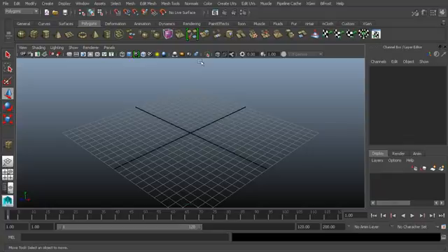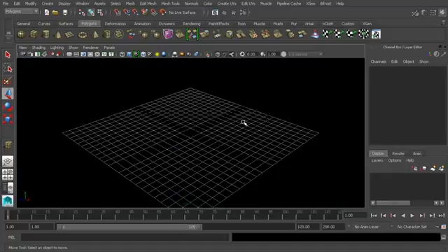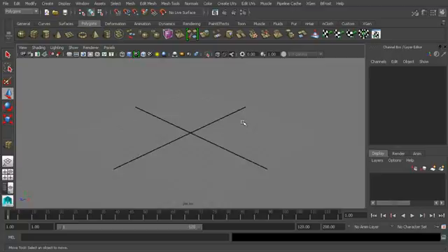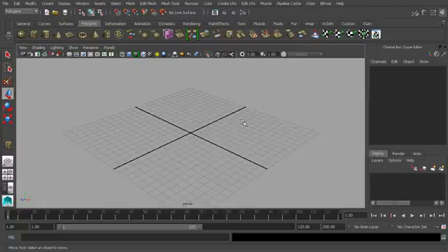Now right now there's a gradient. You can see kind of a blue gradient from top to bottom. There are a couple of ways that we can kind of change this. And I like to turn it off just because it's a little bit clearer in the videos what's going on if we have kind of a plain gray. And so the hotkey to change this is actually Alt-B. You can see I can cycle through black, back to this gray, or this lighter gray,